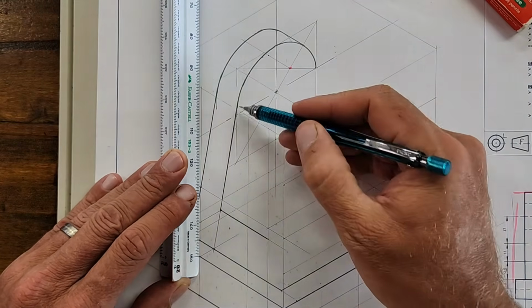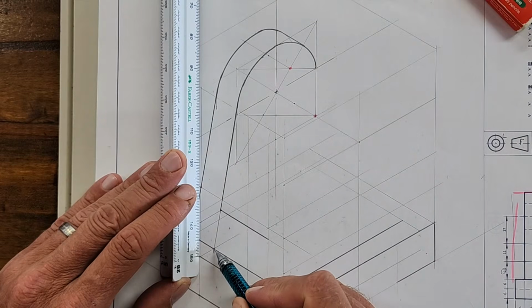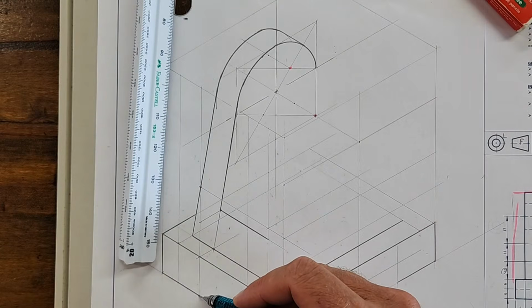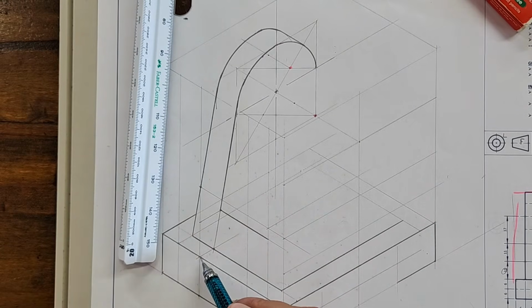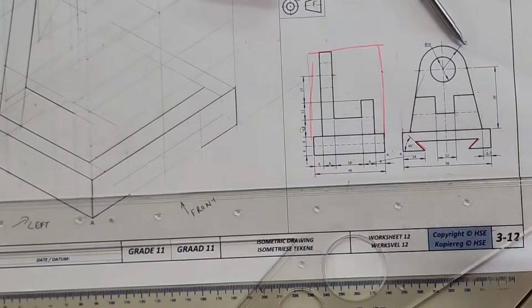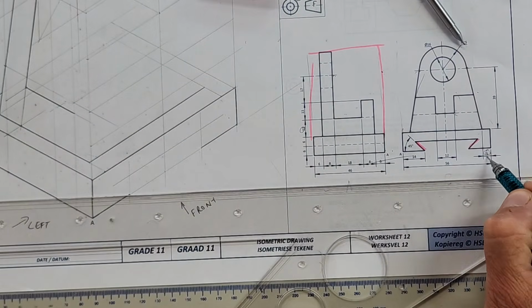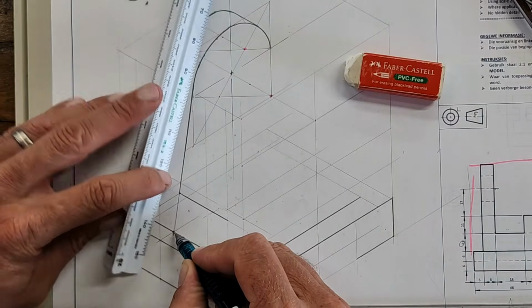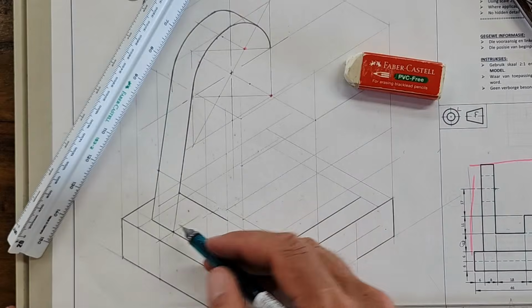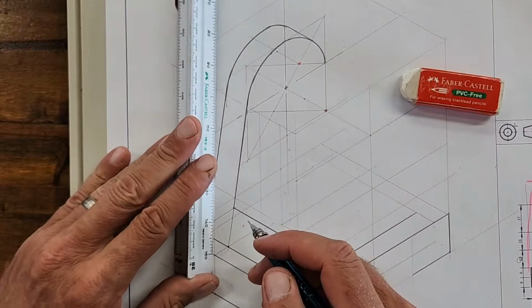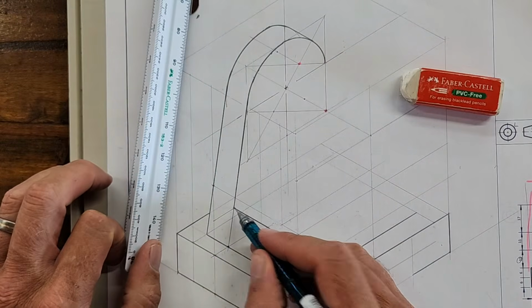Okay. Are you talking about, did you get it at the bottom here? This one. Okay. So you have this 8 going up here. Okay. And then at that height, I'm going to go at 30 degrees. For, if you look at here, it says 5 millimeters. See that? Okay. And then where it meets there, it's a corner. So that's where I aimed for. All right. And then to get that height, the perpendicular height is 11. So there's my 11. Bring that across, and where it meets, that's that corner.